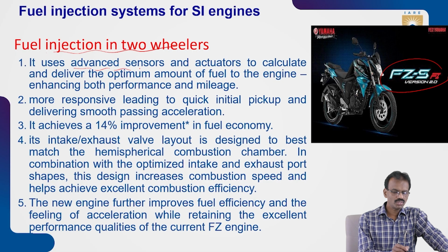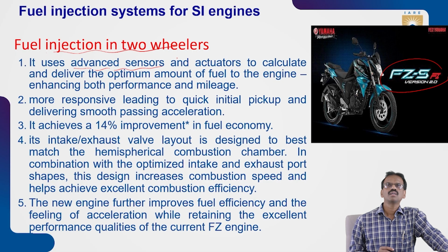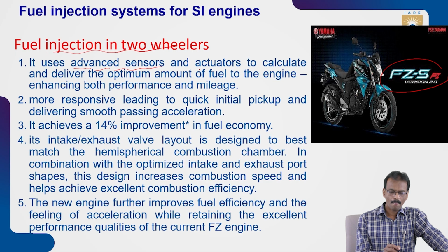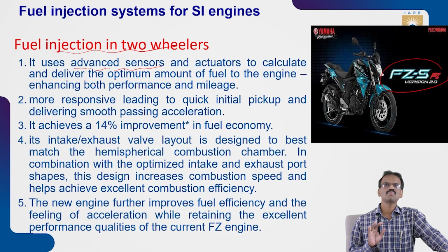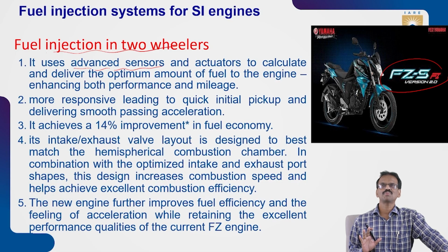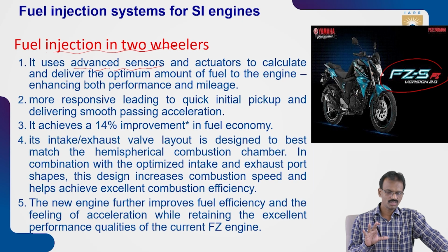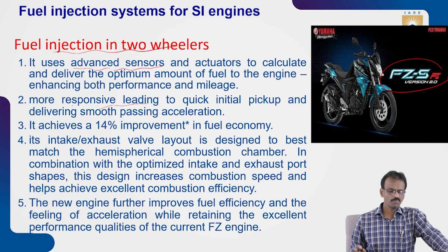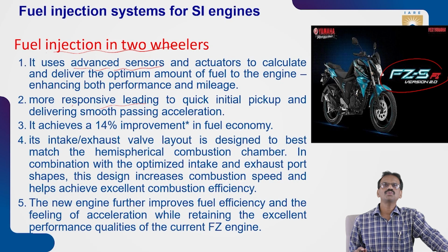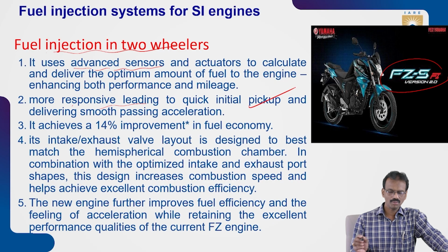It uses advanced sensors and actuators to calculate and deliver the optimized amount of fuel. Optimized amount means the required amount of fuel based upon the climatic conditions and the sensor signals. Next, it is more responsive, leading to quick initial pickup and delivering smooth passing.